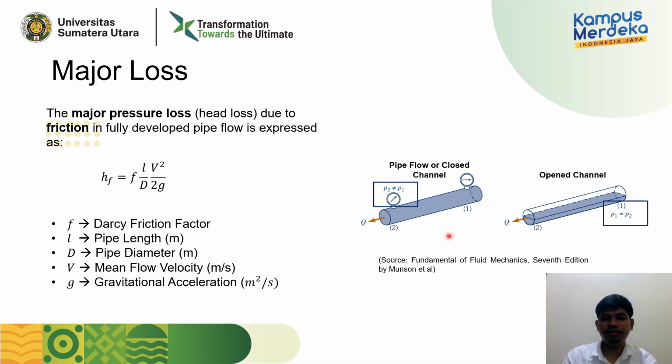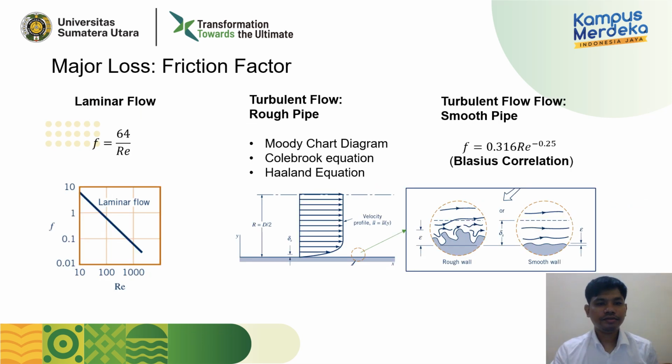To measure the difference in pressure, which we normally call pressure drop, we need to calculate the pressure loss or the head loss with this equation. Like I said before, when we talk about major loss, the most important thing to know is the friction factor.